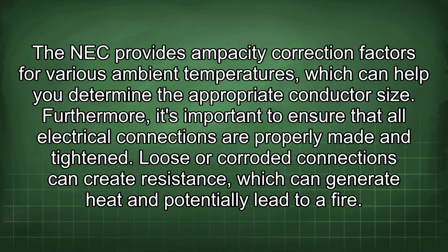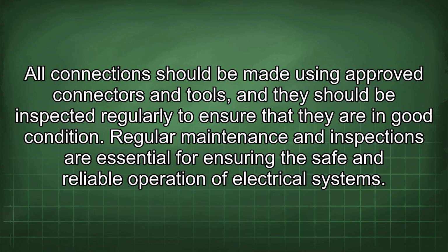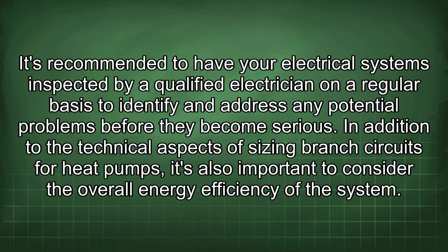Furthermore, it's important to ensure that all electrical connections are properly made and tightened. Loose or corroded connections can create resistance, which can generate heat and potentially lead to a fire. All connections should be made using approved connectors and tools, and they should be inspected regularly to ensure that they are in good condition. Regular maintenance and inspections are essential for ensuring the safe and reliable operation of electrical systems. It's recommended to have your electrical systems inspected by a qualified electrician on a regular basis to identify and address any potential problems before they become serious.